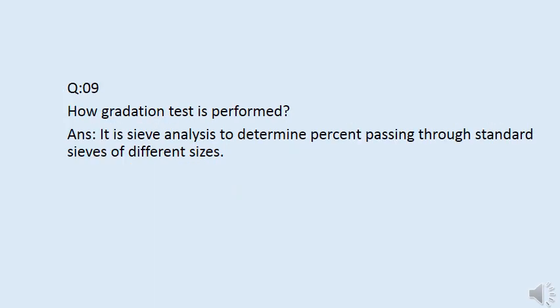Question number 9. How gradation test is performed? It is sieve analysis to determine the percent passing through standard sieves of different sizes. So a curve is drawn between the particle size on x-axis and the percent passing on y-axis.